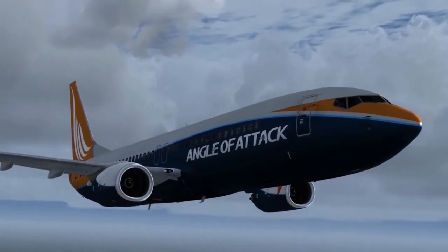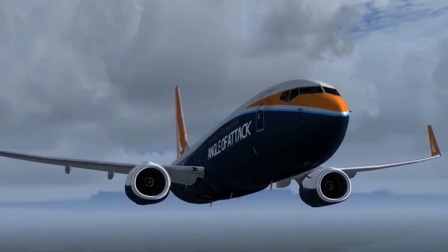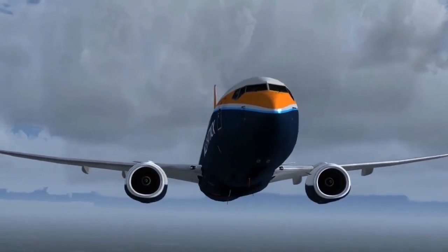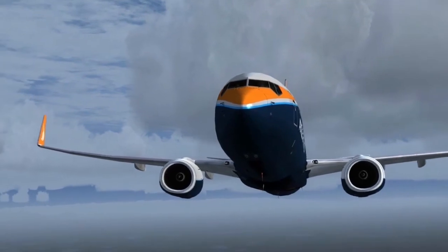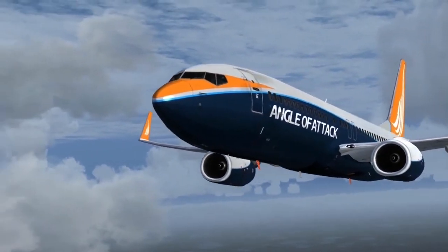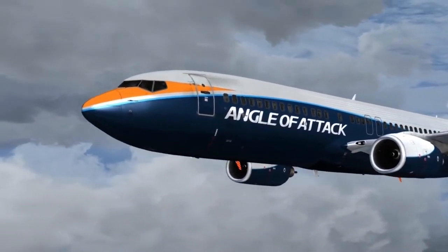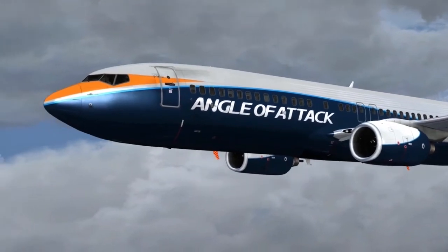We'll finish up here with a lesson summary. The 737 features an impressive level of system redundancy throughout, and the hydraulic system is no exception. Even with complete failure of systems A and B, the aircraft may still be flown through manual reversion, which uses pure mechanical linkages to the elevators and ailerons.